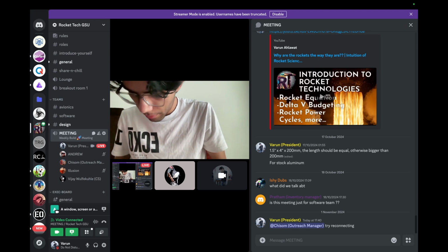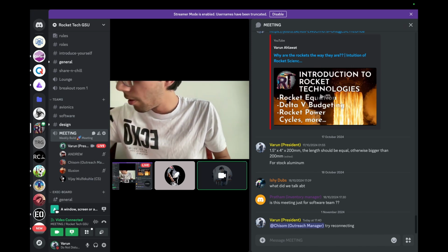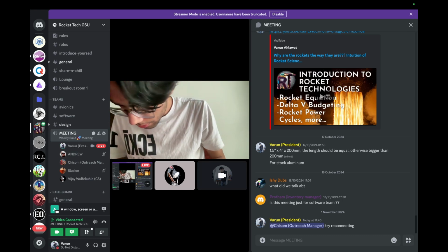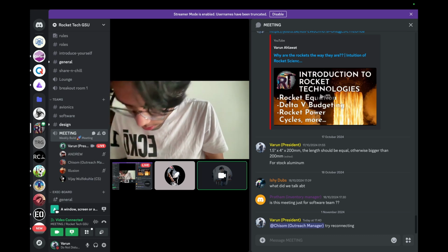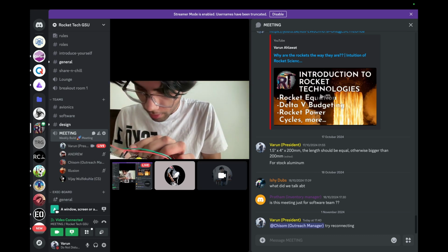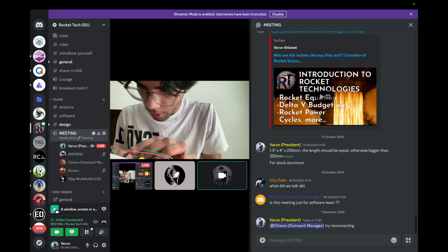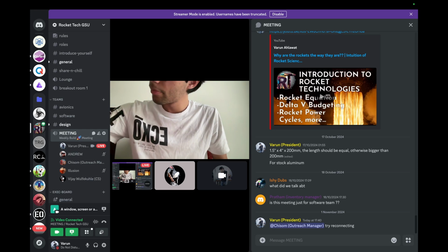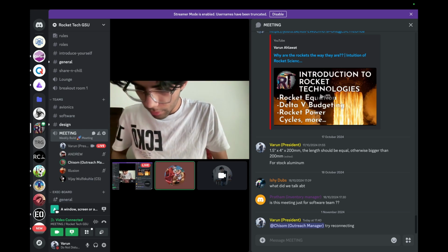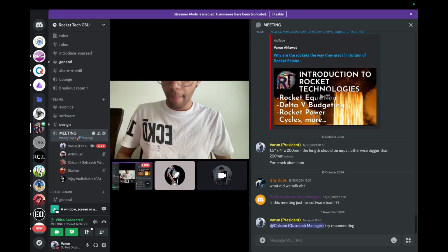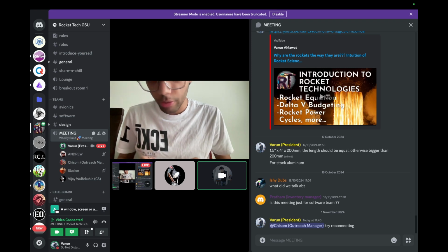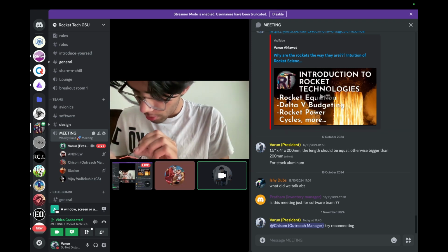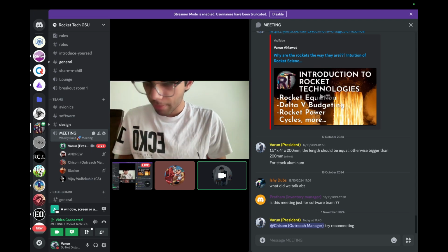Z out. Okay, Z out. Let's choose the orange color for the Z one. And I'm gonna plug that into G21 on the ESP. Can you write it down? Wait, hold on. Yeah, I will. Orange, yeah, orange for Z out, you said, right? Yeah. And I've connected that to G21 on the ESP.